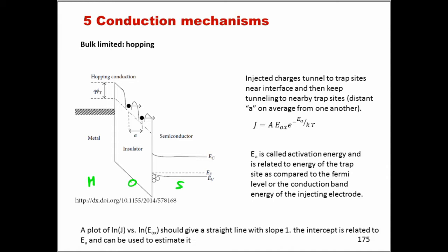So then what could happen is that the electrons from the metal side could, under appropriate biasing conditions like the one depicted here, we are assuming, for example, that we've applied a negative potential on the side of the metal, well, electrons could hop into the closest trap site and then keep effectively hopping into the next one.